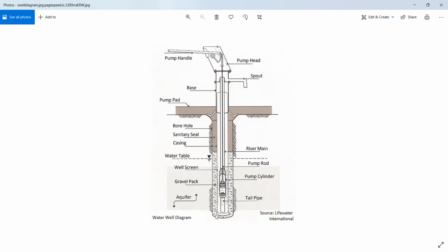The strainer is provided at that end, and the entrance velocity decreases up to 10% of the diameter of the pipe according to the standard, so the water enters into the pipe, but particles like sand should not enter into that rising main, in order to prevent the blockage of pipes.